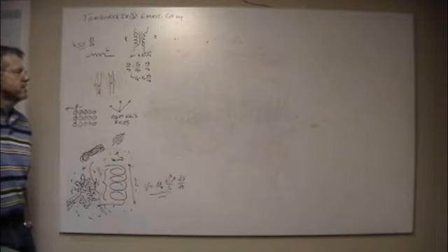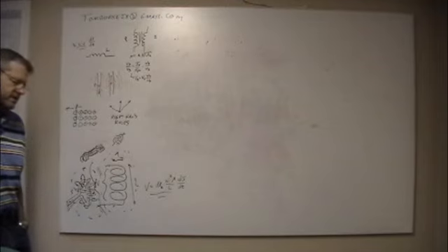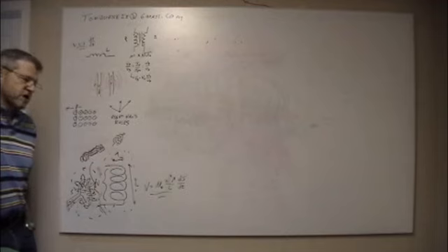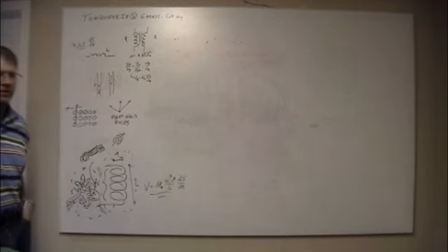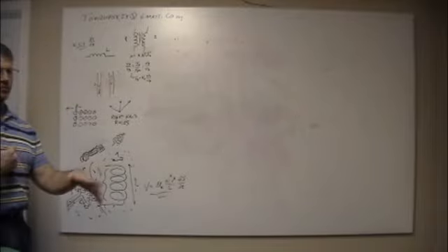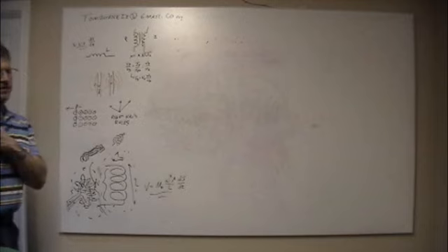What they're getting there is... Well, of course they're not twisted, so I guess they need that. It's just a coax. Yeah. They're using a foil and a braid, and then maybe another... They're probably doing a foil, a braid, a foil, a braid. Braids are good at high frequencies. Foils are a little bit better at lower frequencies, but they're really not all that good because it's a tape that wraps around. So each has its strong points.